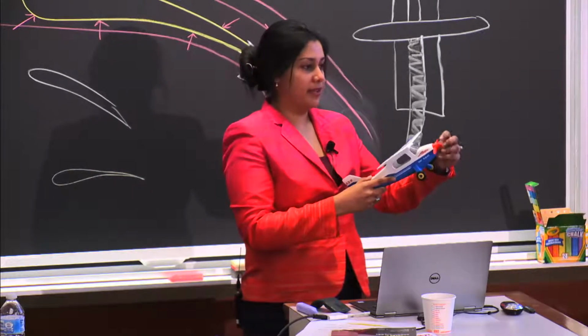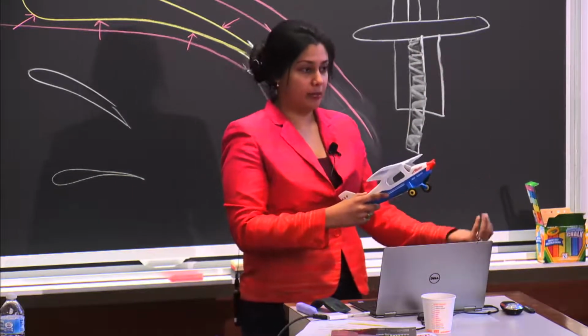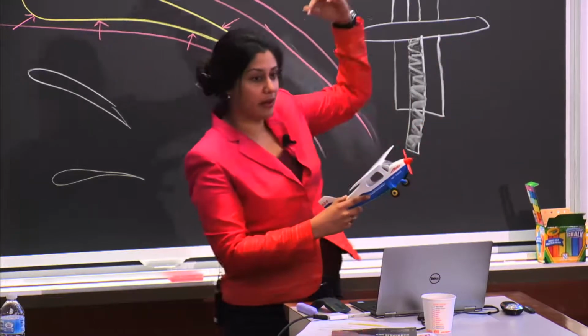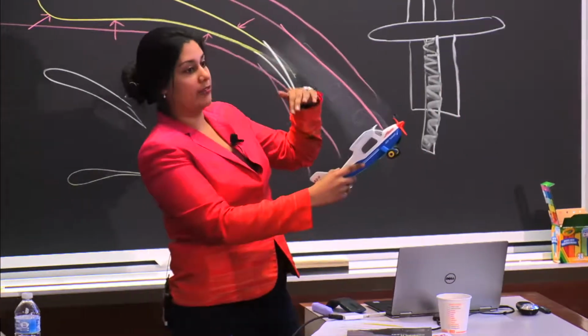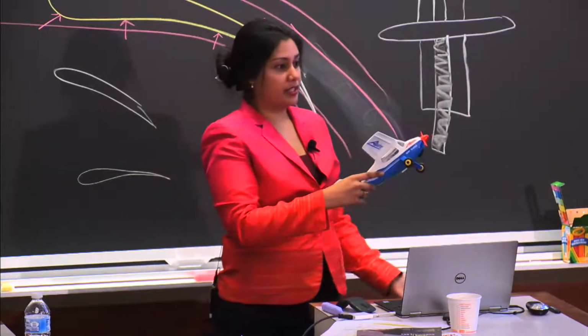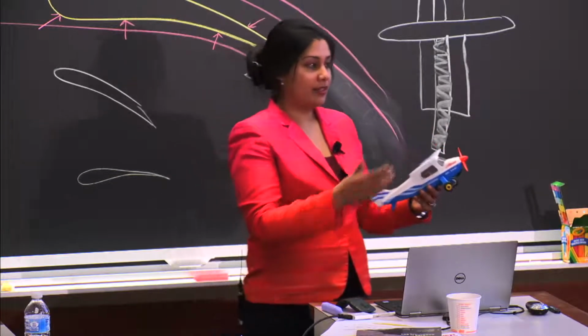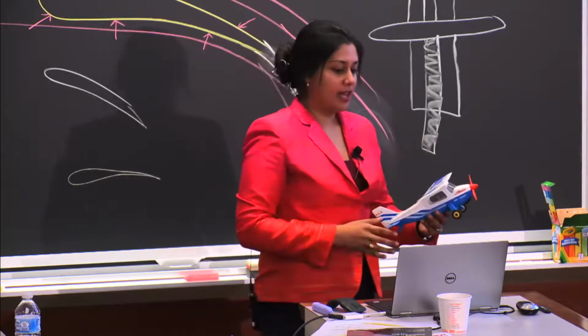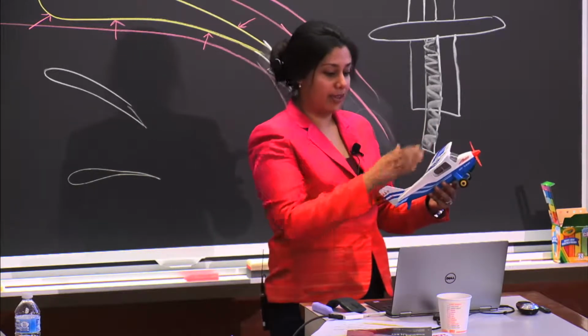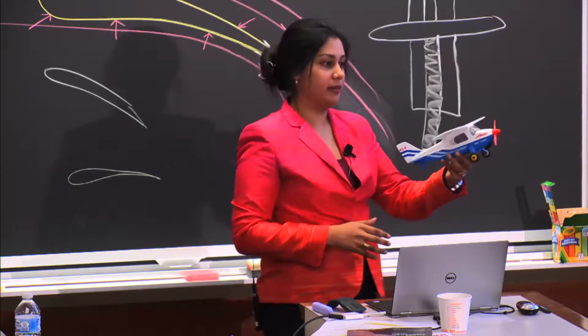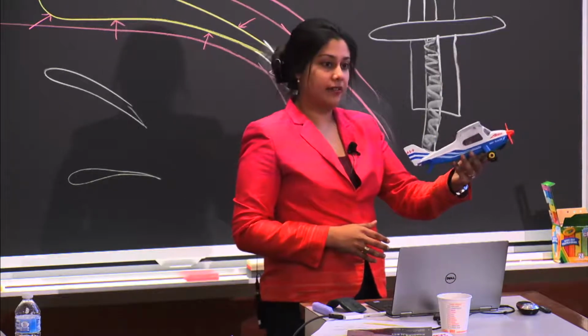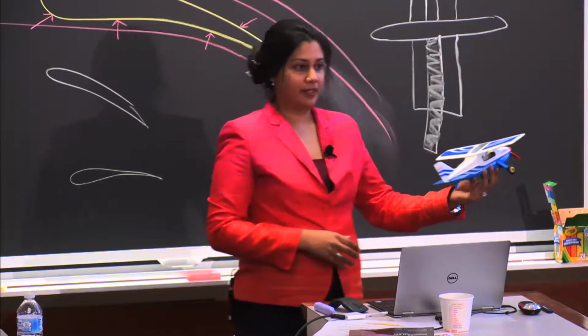Whereas the ascending left propeller blade, the one going up on the left side, is coming away from the wind that's coming at it, and so it's not generating as much thrust as the right propeller blade. That causes the center of thrust to move towards the right, and that creates a little bit of a yaw tendency of the airplane. Does that make sense?